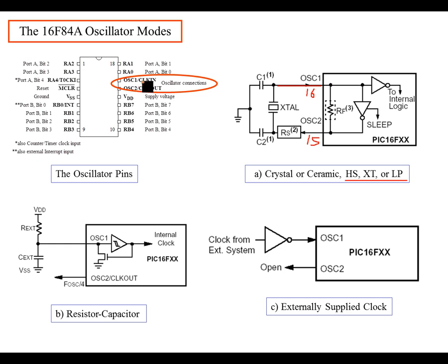When you're designing this, you're going to want to have your crystal oscillator here, your capacitors here, and then route directly to your board, from your chip to your board. Make these connections short. You don't want to have your crystal way over here and your capacitors here, and then have long wires leading all the way to here. That's going to change the resonating frequency of this.